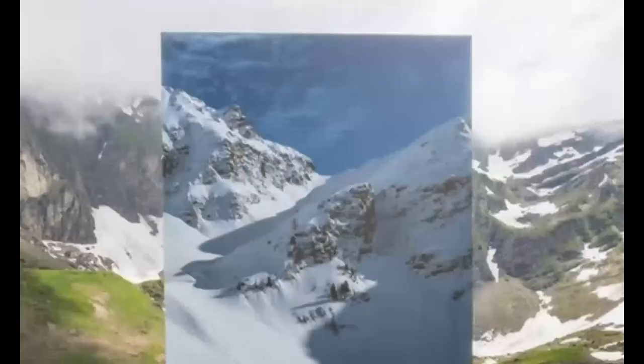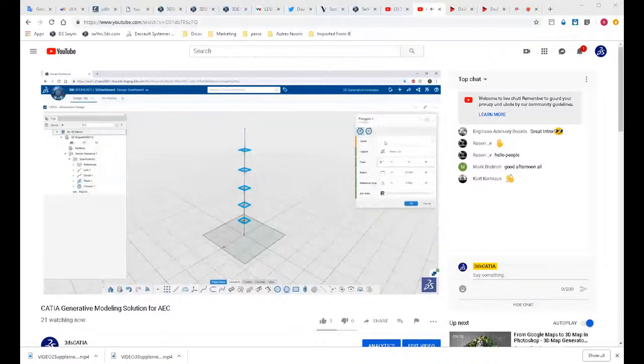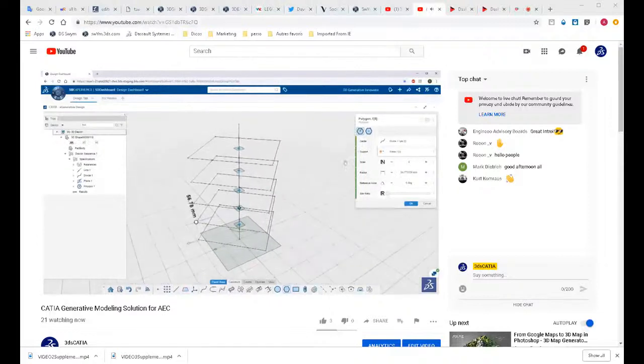Geometrical operators are able to work on collections of objects. So when you divide a line, curve, or surface, you get a list of points. You can immediately reuse this list of items to build additional lists of items, including points, planes, and surfaces. The planes generated here are used as support for polygons, that you can access one by one.